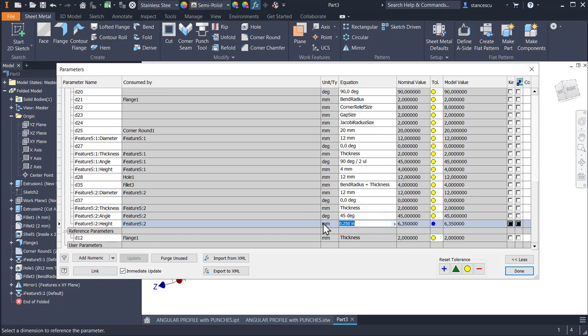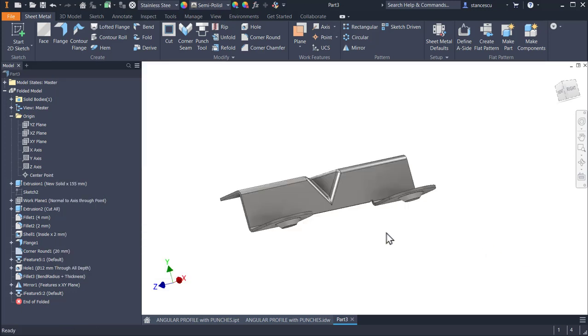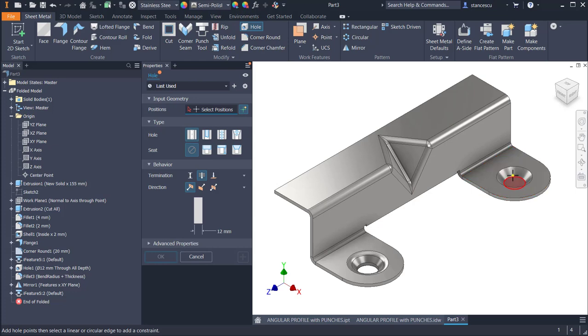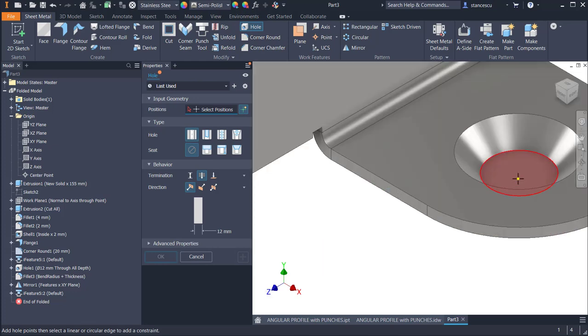You see millimeters are here. This is why the dimension is finished with IN from inches. So 4 is the value. Done. We apply hole. Where is the hole? We select the face, we select the center, and the value and the through are already selected. Okay.